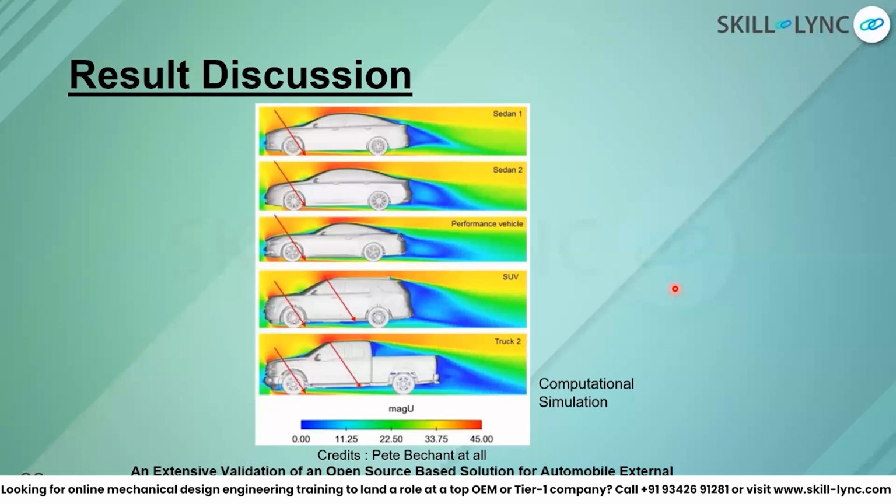But again, are you trying to understand the flow physics, or the heat transfer? Because if there is exhaust geometry on the body, there's heat transfer. You want to cool down those parts, or you are only interested in the aerodynamic performance of the car.